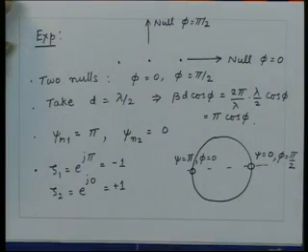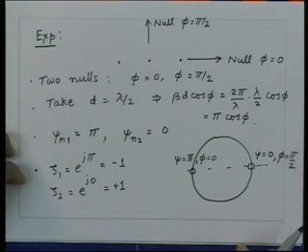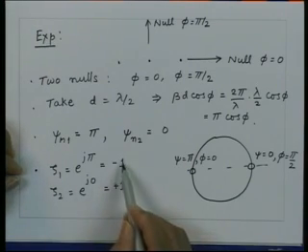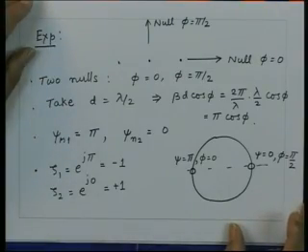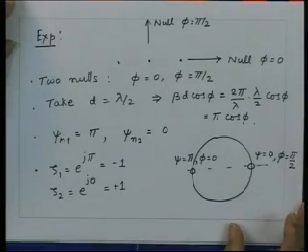So, now if I take the roots which are minus 1 and plus 1, then we can define the polynomial which will be z plus 1, z minus 1, and if I expand that polynomial, that would correspond to the excitation of the array elements.